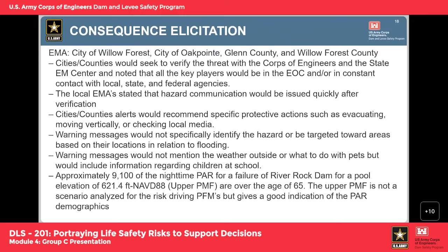Okay, so our downstream consequence centers mainly focus on the city of Willow Forest, the city of Oak Point, and then Glenn County and Willow Forest County. We did have a consequence elicitation performed with these different groups. Willow Forest and Oak Point are located approximately 10 miles and 38 miles downstream respectively, and they have flood wave arrival times of 1 to 3 hours respectively. So going back to that seismic failure mode, we have a pretty sizable flood wave coming through that gets to these consequence centers very quickly.